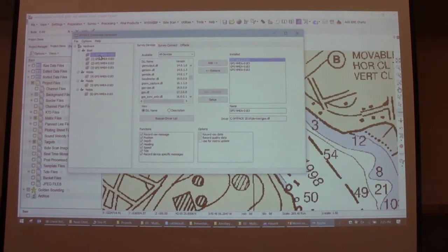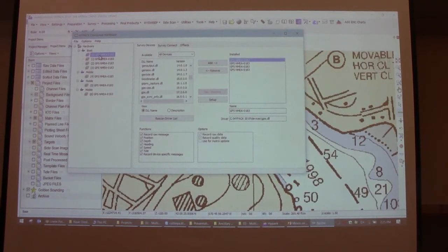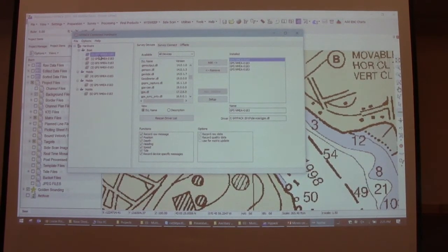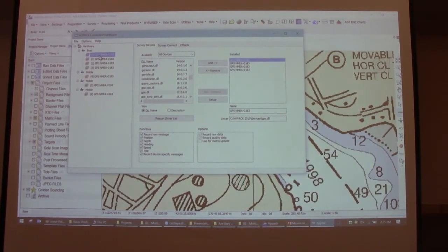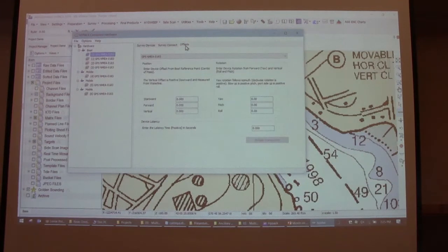I'd like to see how you had it set up before, if you had that checkbox under hardware, individual tides per mobile. Yeah, well, the core main version of the Multibeam was to add a couple of transducers across the boat and use the one GPS and then do the others as offsets. And when you do your other transducers and fathometers as offsets. Okay. And under the top version where you add it all under one boat, it only would show you just the one transducer where the depths are coming from. It wouldn't show you the offset transducers. So even when you had offsets here, yep.